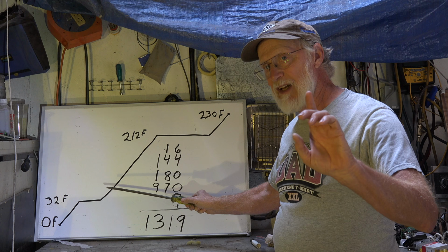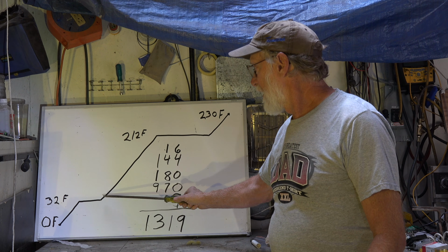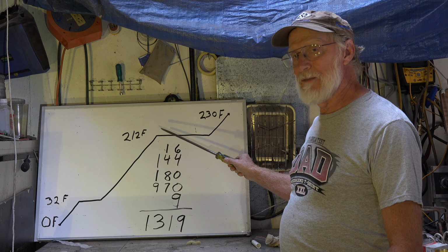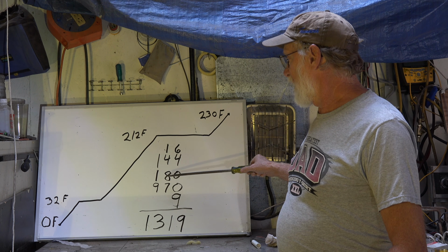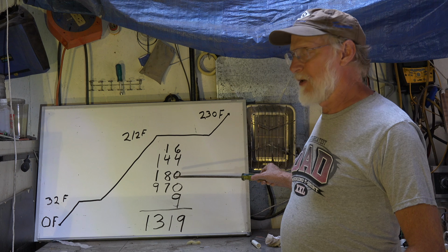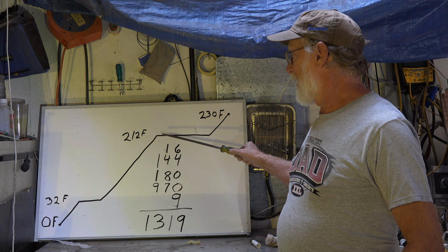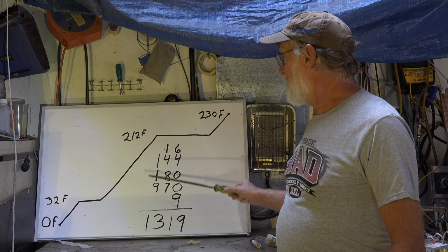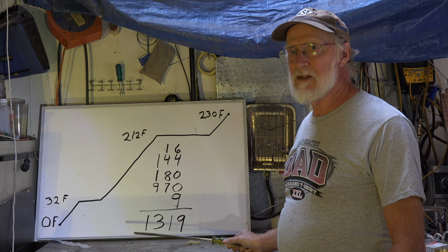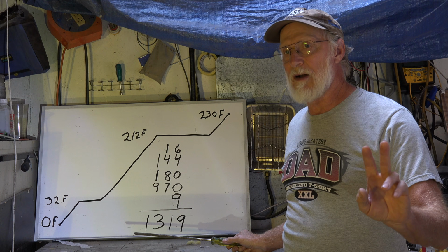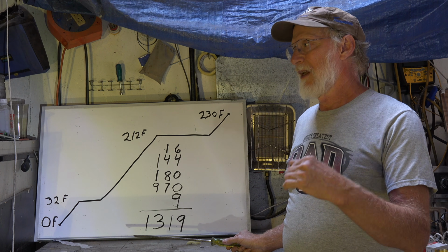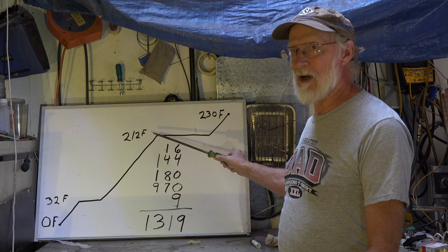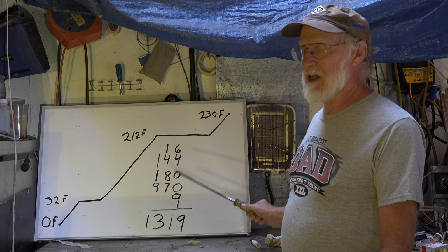Water has a specific heat of 1. Now we're going to raise that temperature, of course another angled line, and we're going to raise it 180 degrees. It's absorbing sensible heat. Once that thing reaches 212 degrees, it can no longer be water as a liquid. It has to be steam. You cannot raise its temperature above 212 until it becomes steam.